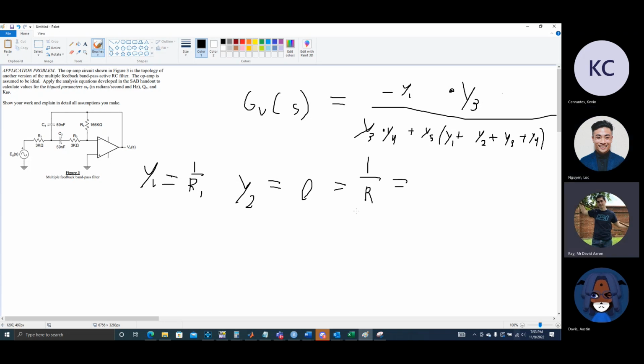If we were to solve for this, R is going to be equal to infinity. And if the resistance is infinity, then that means that it's an open. So maybe there was something over here that went off as a resistor and then connected to ground. And because it was not there in the circuit, y2 is equal to 0, because the impedance for that would have been enough to completely make that part an open in the circuit. And so that's why y2 is probably equal to 0.